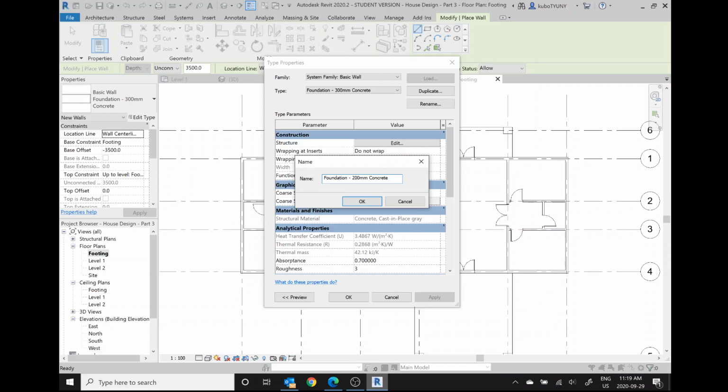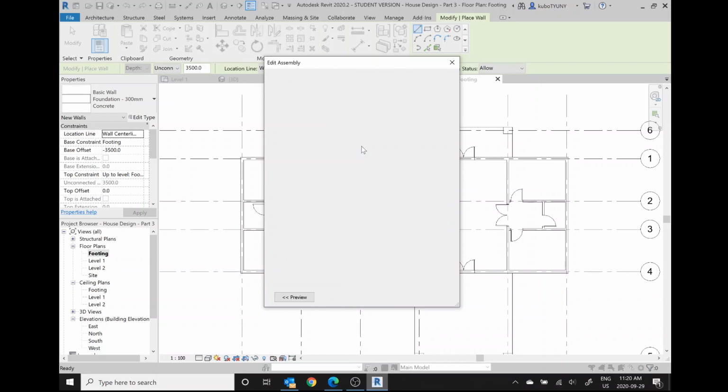200 millimeters is nice because for any house that would be about standard, unless you have strange geological conditions where there's a lot of mud, or you might have some sinking soil in some cases. In that case, you might want the footing of the house to be a little bit stronger. But we're just going to assume this is a generic, cookie cutter type of house on normal conditions. So it's going to be a 200 millimeter concrete foundation wall with a strip footing on the bottom. We'll add that later. And since it's 200 millimeters concrete, it can either be 200 millimeter concrete block, or it can be a poured wall. In this case, we're not going to specify. We're just going to say it's 200 millimeters.